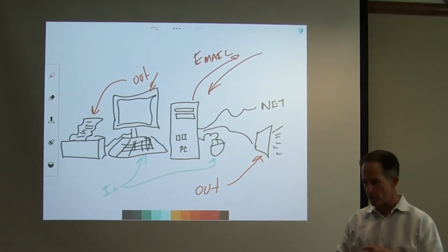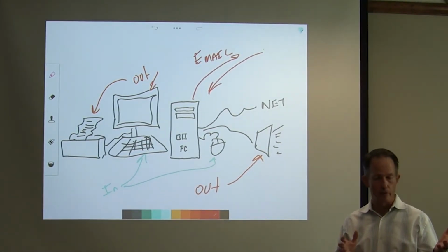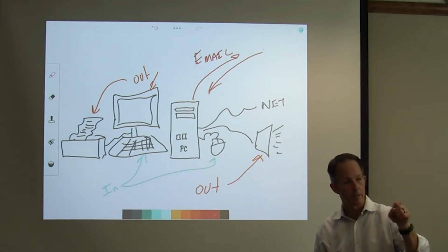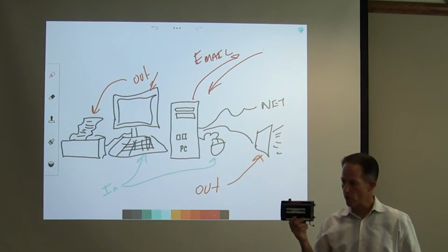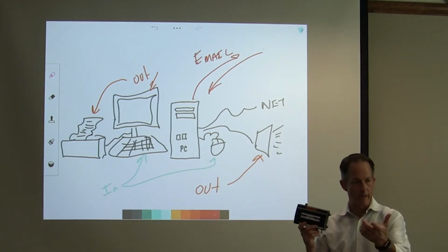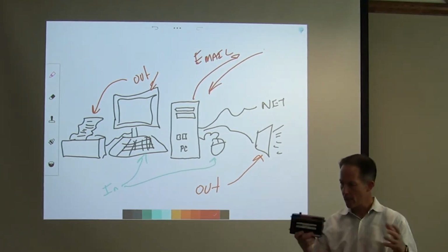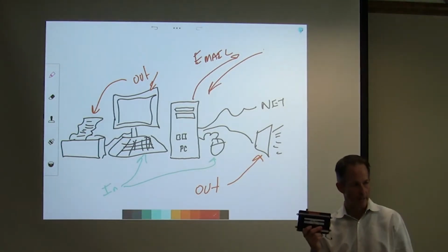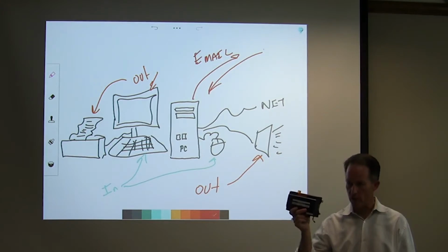We have various controllers that are out there. We have some Johnson that are on campus. We have what's called an NAE, or what's the other one? NCE? NCE. Okay, so those are very similar to our Jace controllers. The NCE I believe has inputs and outputs tied to it as well, is that right? The NAE is mostly a collecting of data, and then it serves as a network interface to get back to the head end. Network access engine, network controller. Okay, so there you go. And so those function much like a Jace in what they do.